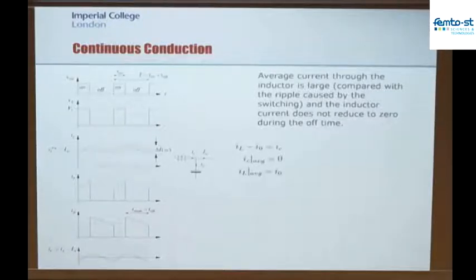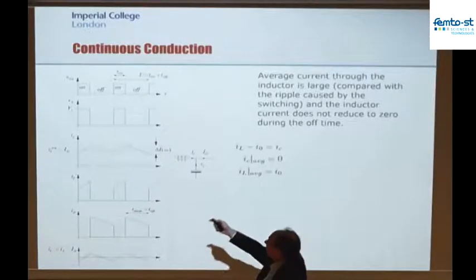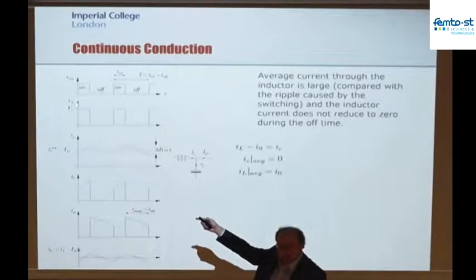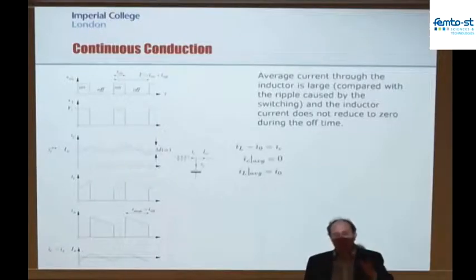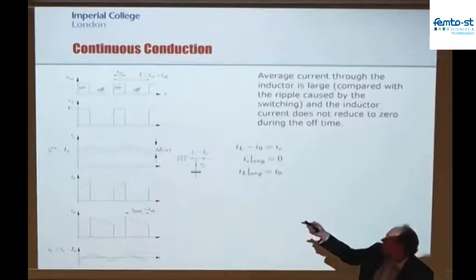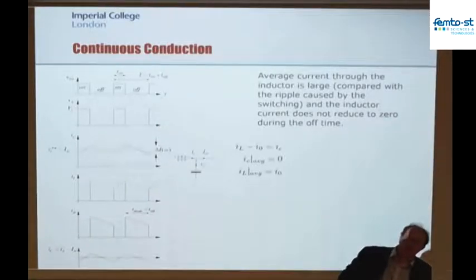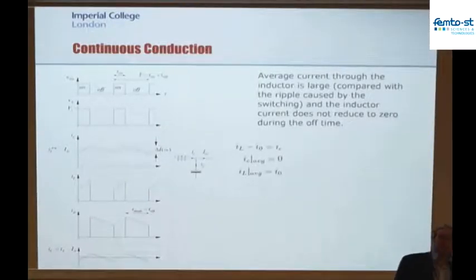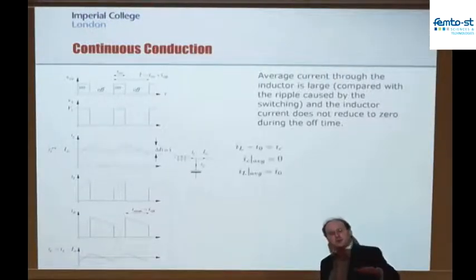So if you didn't have the low-pass filter, then actually this would be the voltage that you would see at the output, the voltage at Vx, which is this pulsed. It's changing between V in and 0, V in and 0. So the average value of that is the voltage we're after, but our circuitry wants a constant voltage. So we're powering a microprocessor or a sensor from our power processing circuit, and we've got to be able to do that directly from a smooth, nice, steady DC voltage like you get from a battery.